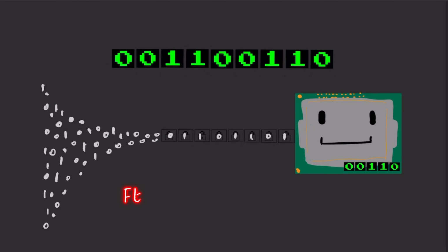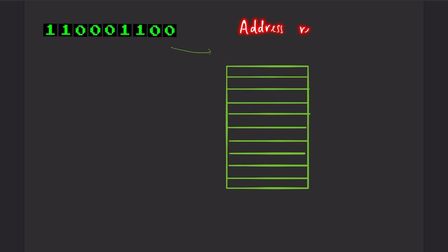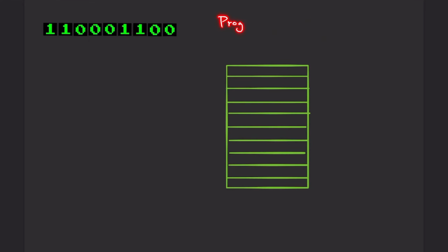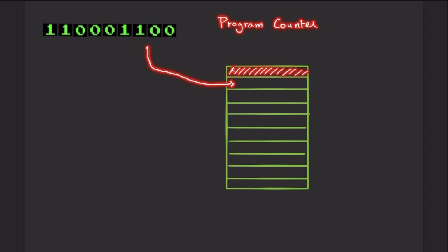Whenever the CPU gets the data or executes the instruction code, a cycle known as the fetch, decode, execute instruction cycle takes place. The computer needs processor registers, otherwise known as accumulator, for manipulating data and an address register for holding memory address. The register holding the memory location of the address of the next instruction that is to be executed when the current instruction is completed is called program counter.